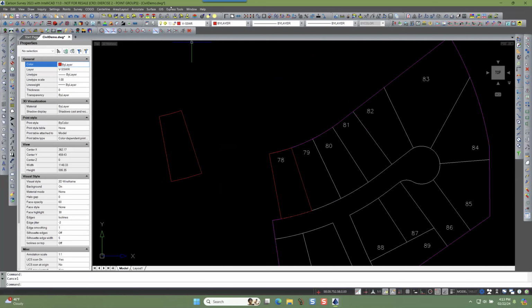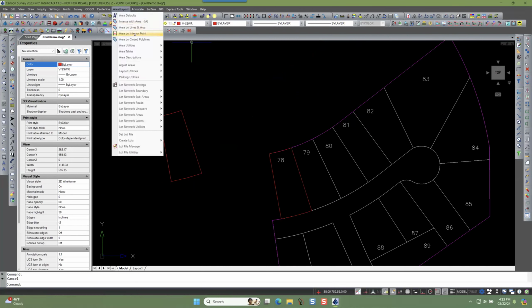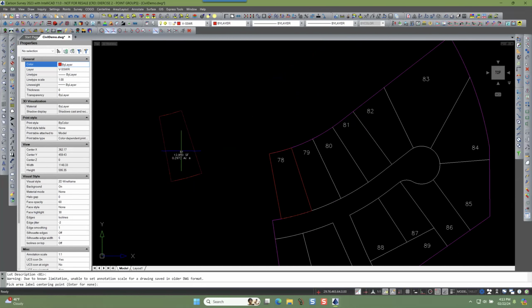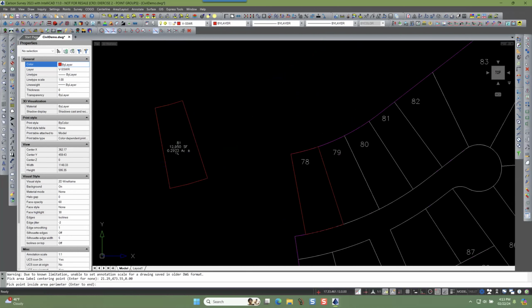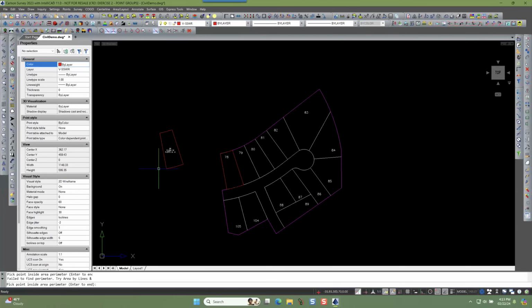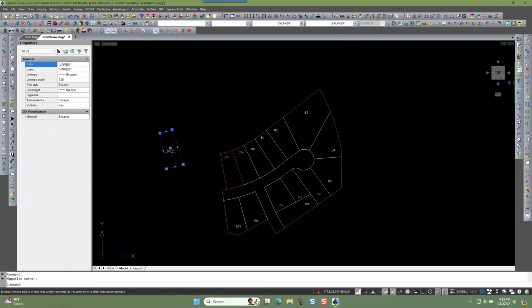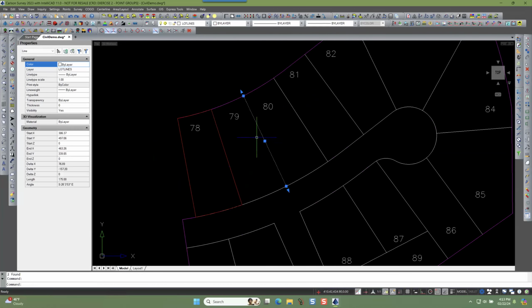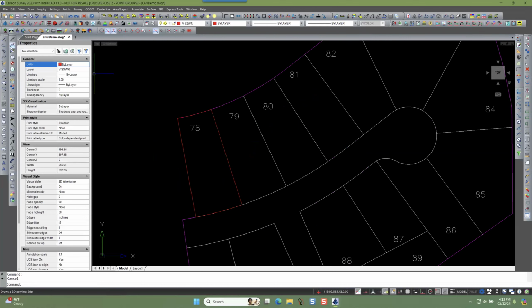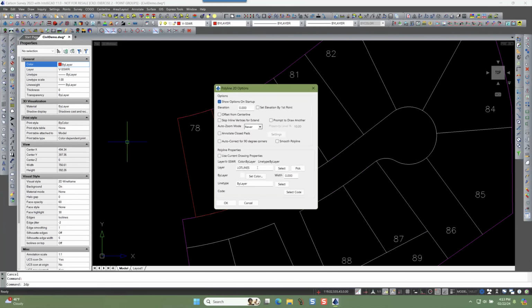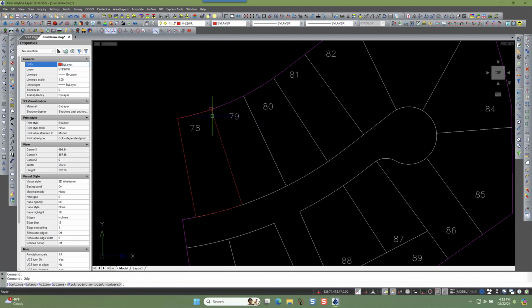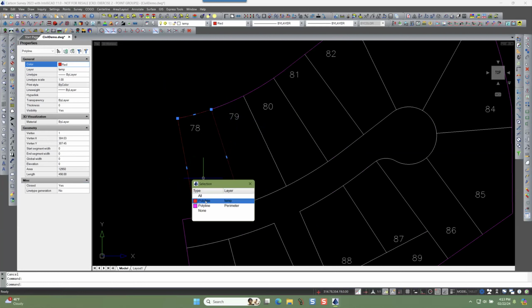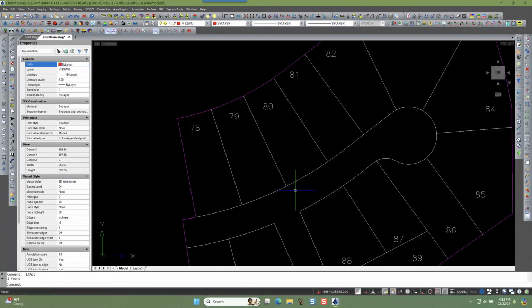Yes, it's closed. So I do by interior point that way. All right, so there's the 12,950. So it is correct now. I must have missed something in there. So I'm going to take now this particular line. I'm going to draw a 2D polyline from that point to that point, and now get rid of this red line that I no longer need.